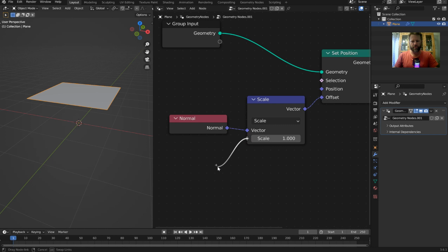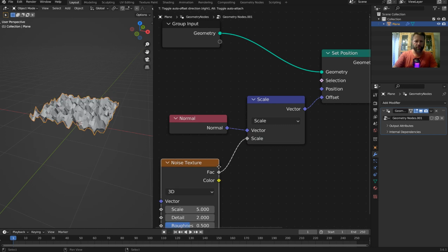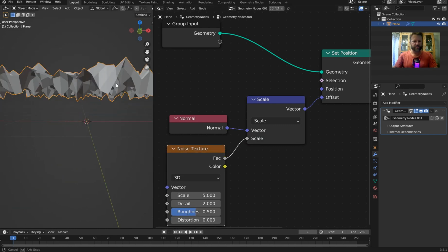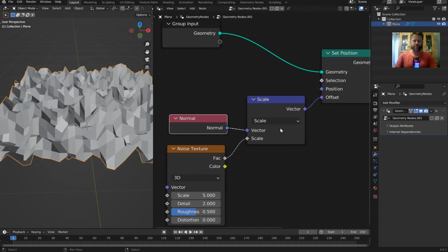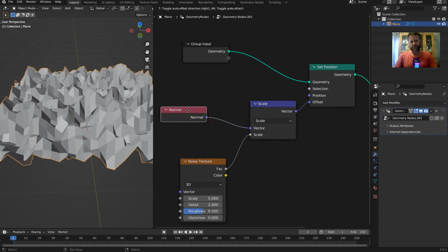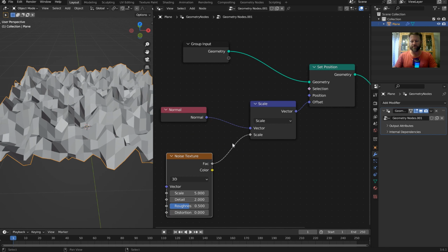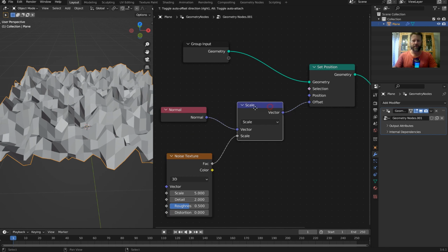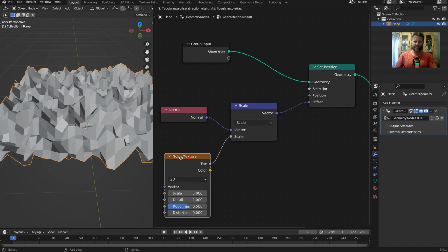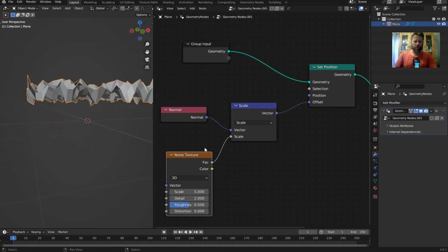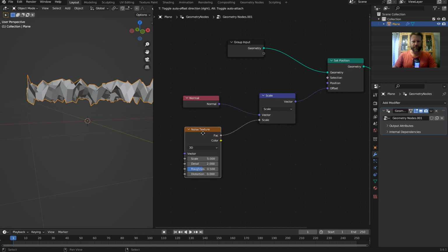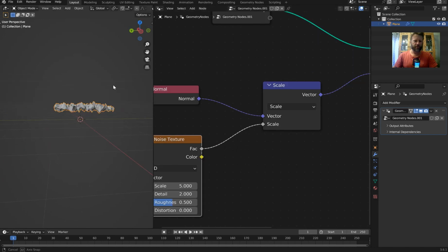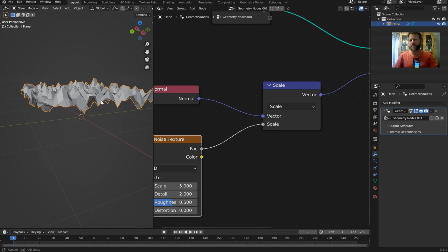And for this one, we can pull this out and type in noise. And then we get a noise texture that is 100% on the z-axis. So if I take this off, you don't see anything. You do, then you've got the displacement. Now, as far as this goes, this is just a single value going into the scale. So we don't necessarily have to do a whole lot to it, but I do want to take this noise texture and correct basically the mid-level, okay?